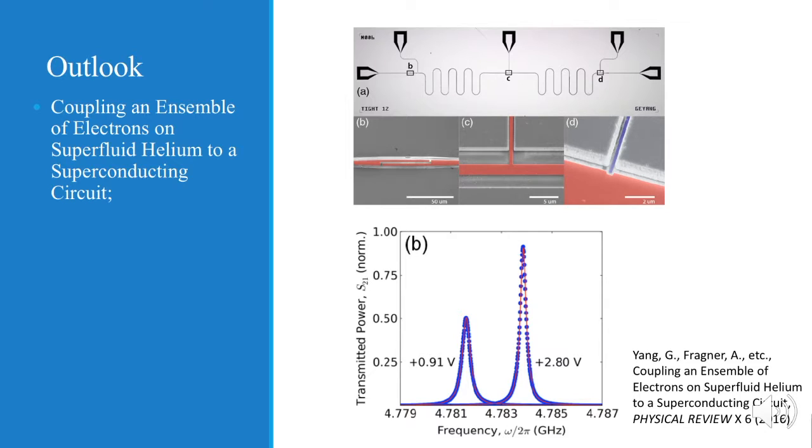So in this hybrid approach, electrons are trapped above an on-chip superconducting microwave resonator. The presence of the electrons changes the effective capacitance of the cavity, resulting in the dispersive shift of the cavity resonance frequency, which is shown in figure B.